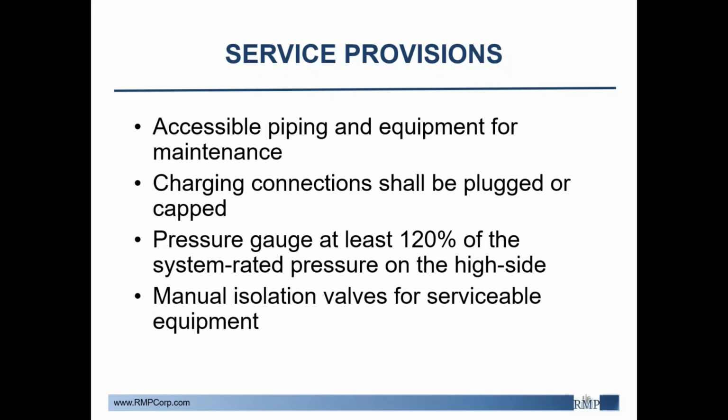Pressure gauge allowances on the high side to be able to have the allowance needed, so you don't have pressure gauges going off at random times or at your alarm set. Your alarm set point should match up. Also, isolation valves. They bring in a lot more isolation valves on your equipment so you can isolate those and take them offline as needed, especially for package systems.